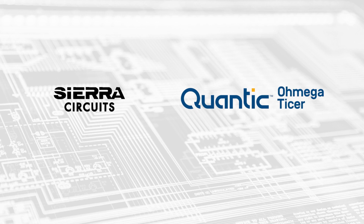And so it's worst case scenario, because if it's embedded, you also typically have copper layers above and below it, as well as the prepreg, which help absorb some of the energy. So we derate it. So we're worst scenario, plus we also derate it at least 25%. So typically it can handle more power.